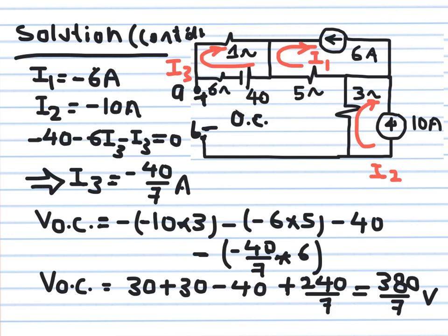Okay, so I created an open circuit. As you can see here, I have now points A and B, and my target is to find VAB. Find the voltage difference between A and B here. So this is open circuit, okay? And the way I decided to do it, I decided to use loop analysis. Well, why did I do that? Because I can see that there is a current source here, there is a current source here, and I can immediately eliminate two equations from these current sources.